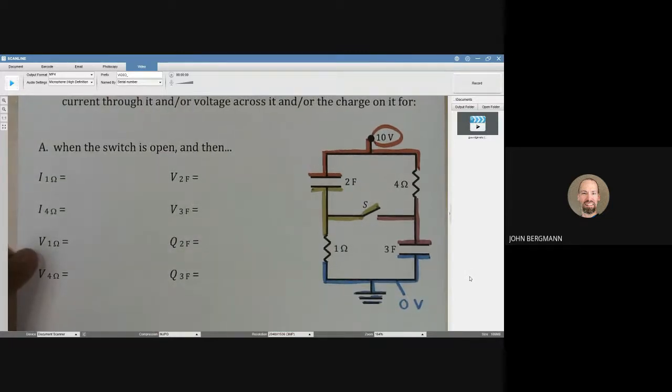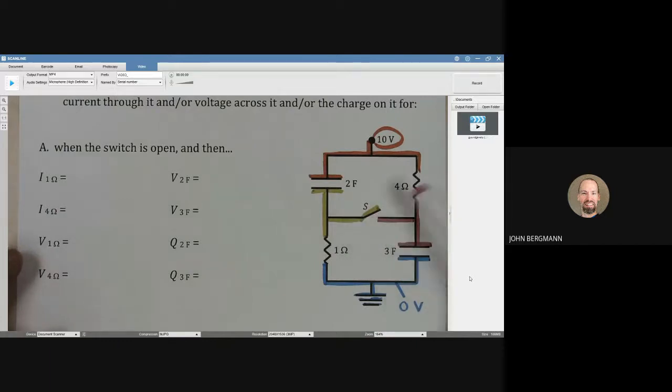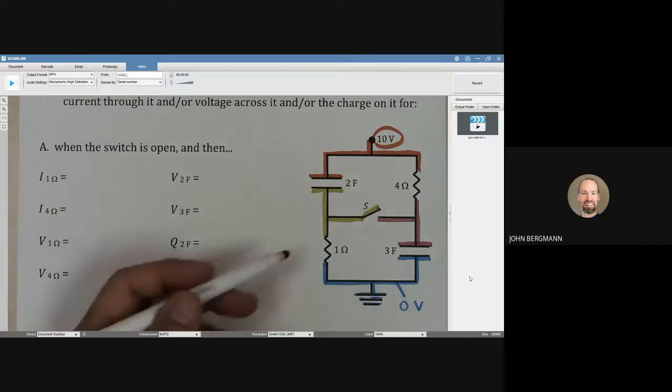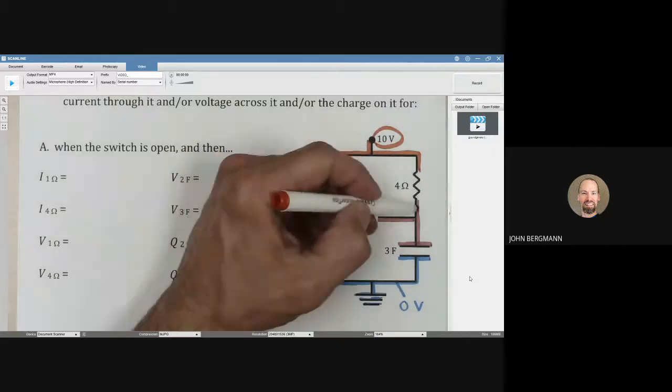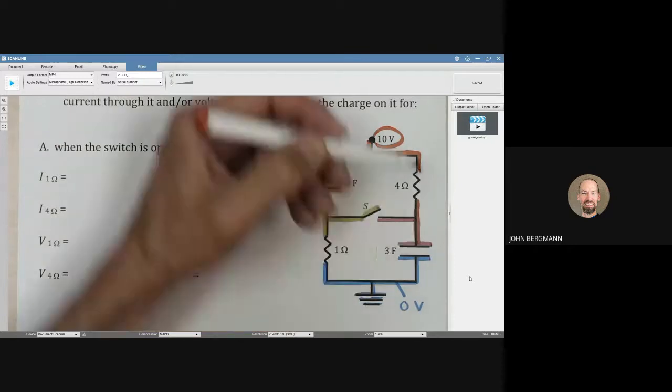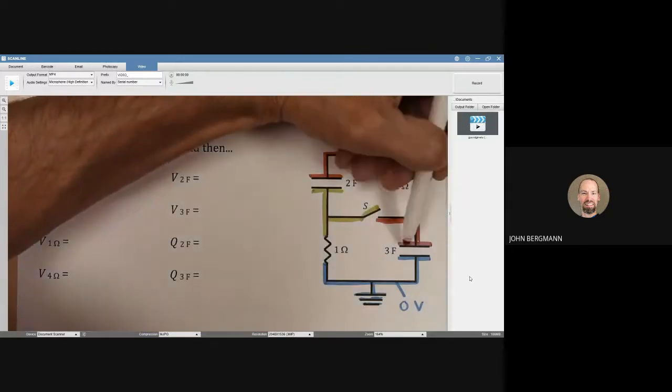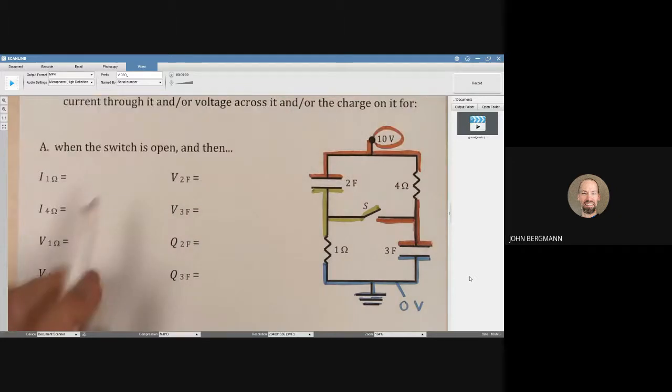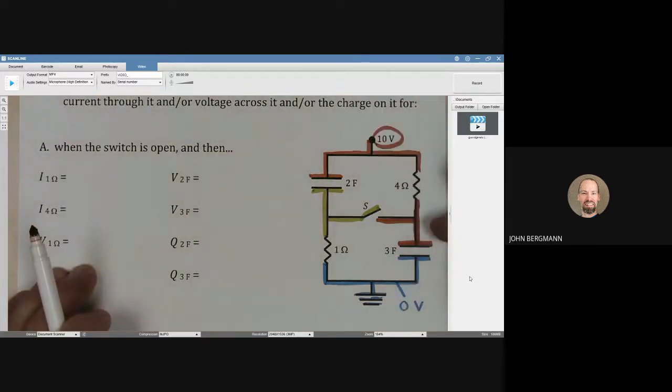I'm looking at this circuit and I'm seeing that there can be no charge flowing through it here at first, because we have an insulator there, we have a break there. So actually what happens here at the beginning is, because we don't have any current actually flowing, it doesn't take very long before this whole region will have a potential of 10 volts.